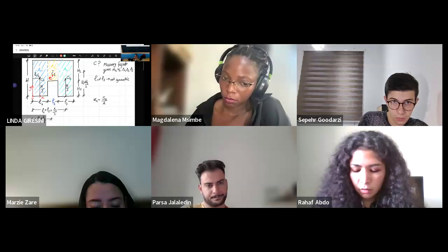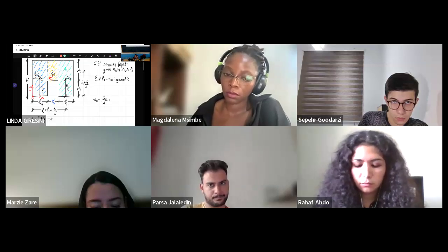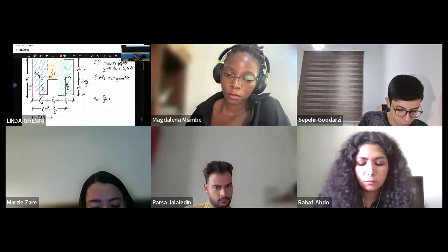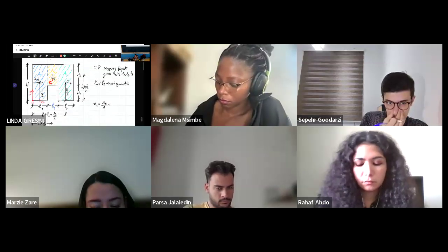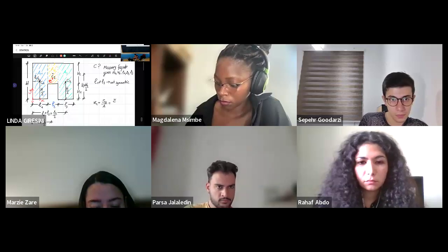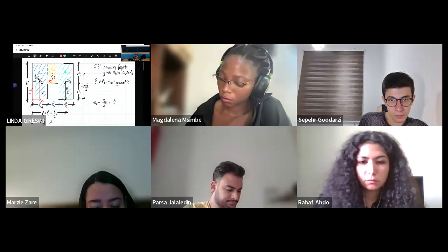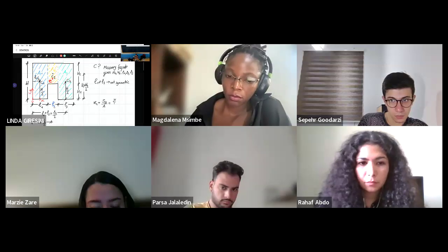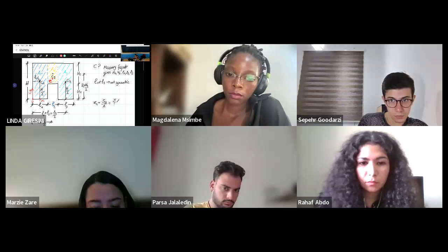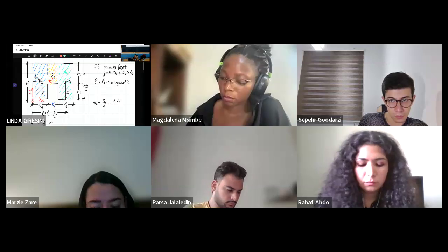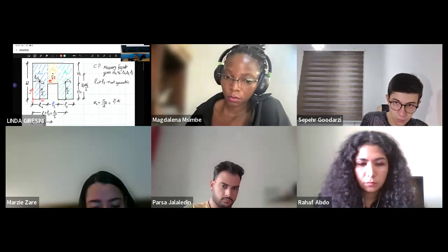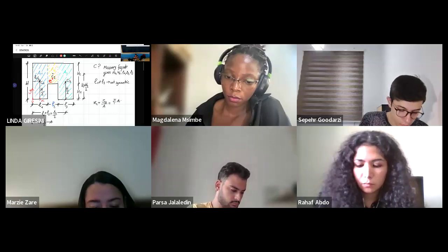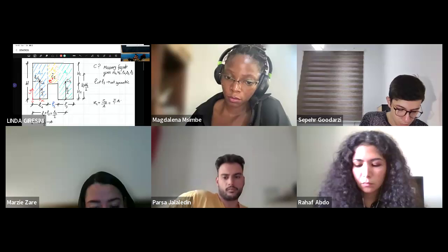So basically, let's start from SY. As we said, for SY, we have to take the sum for the i areas, which are how many in this case? 3? Perfect. So Ai, the area, times the distances of the centroids of each area from the y-axis.